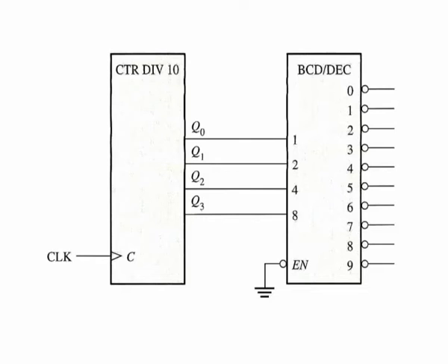These transitional states produce undesired voltage spikes of short duration, called glitches, on the output of a decoder connected to the counter. The glitch problem can also occur to some degree with synchronous counters because the propagation delays from the clock to the Q outputs of each flip-flop in a counter can vary slightly.